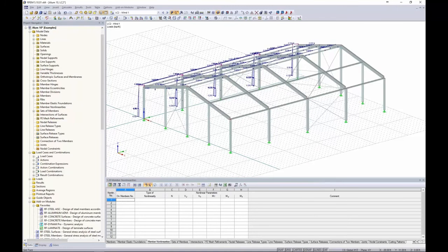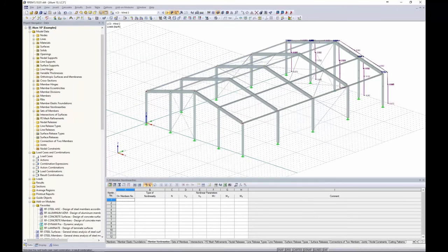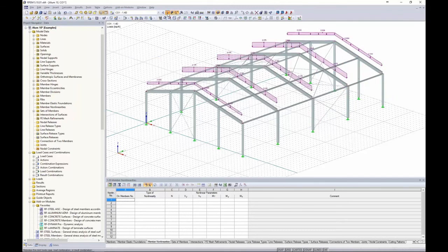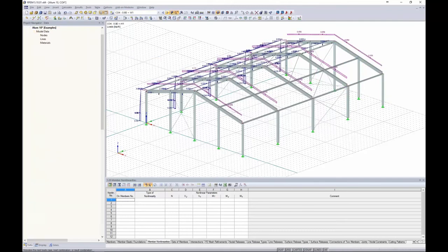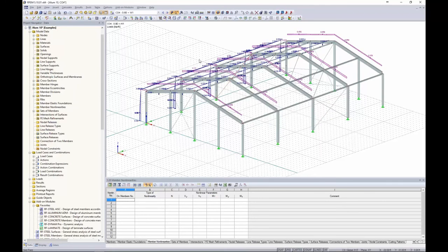Now you can see those wind loads applied for LC2 and LC3. We can always right-click to group those together as an area load as well if we want to make it a little bit of a cleaner look. So realistically, we are done loading the structure. You can scroll through these different load combinations and see how both dead load and the wind loads will be applied, including the load factors.